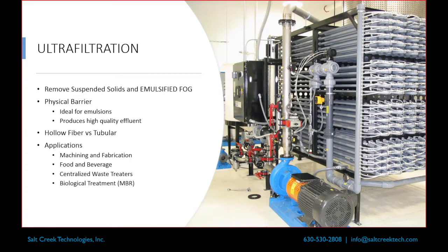The other type of ultrafiltration that you run into a lot is hollow fiber. Hollow fiber ultrafiltration looks like a stack of straws packed into a pressure vessel. Great on the water side, and can be good on the tertiary, like if you're trying to just do a polishing step on the back end of your wastewater treatment system. Not so great for primary application. You really don't want to try and do much with hollow fiber at that step because you're going to end up with a packed full membrane that's useless within a fairly quick time frame.